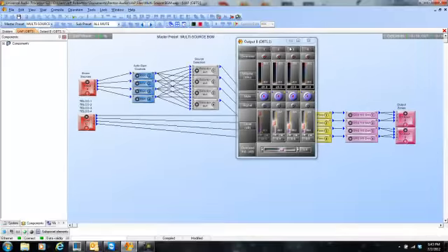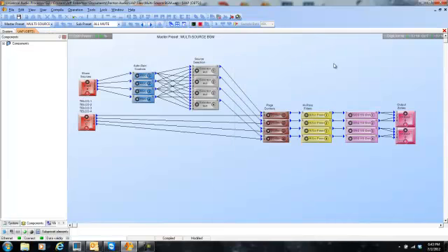There you go. That's a quick, easy tutorial on how to calibrate your analog control devices, because they're going to have different wire lengths, different wire gauges, and different resistive values based on the line loss or impedance loss in the cable. This is the way to make sure all your volume controls and all of your selector switches out there in your installation are running perfectly. So don't forget about the VR calibration.